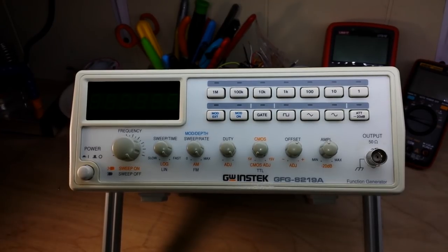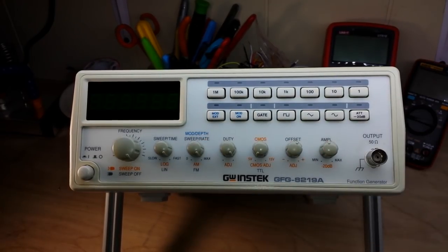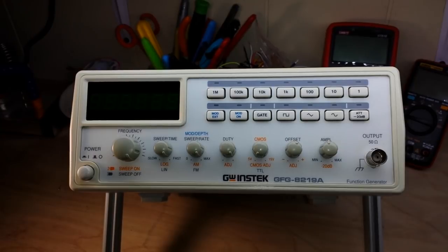It is an analog function generator, and we'll go over the difference between an analog and a digital function generator later. But let's just real quick hit on the high points. It is 0.3 hertz to 3 megahertz over 7 ranges, 10 volts peak to peak, 50 ohm impedance. It's got minus 20 decibels of attenuation, minus 5 to 5 volt DC offset, 20 to 80% duty cycle,